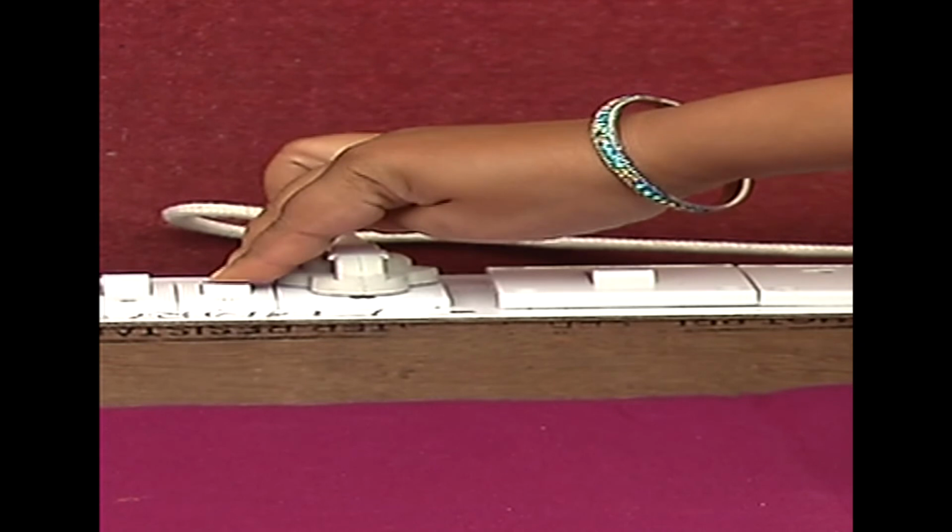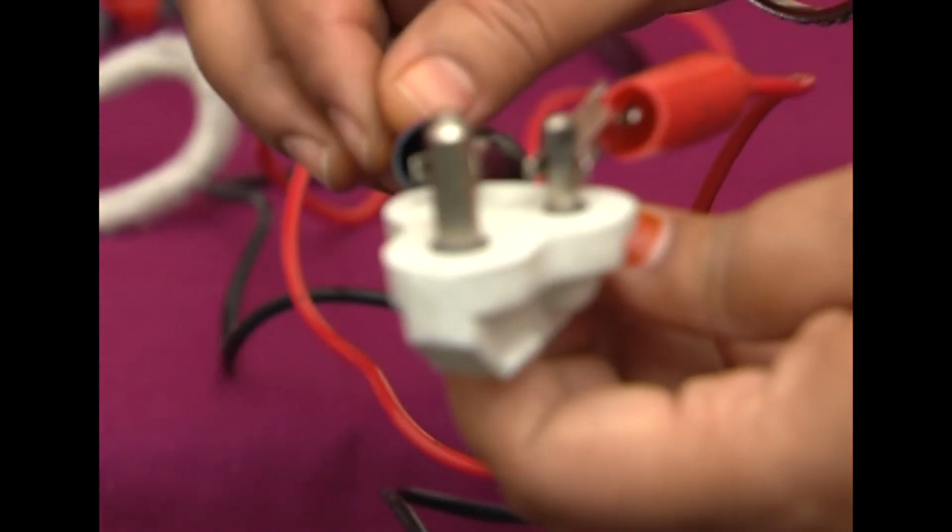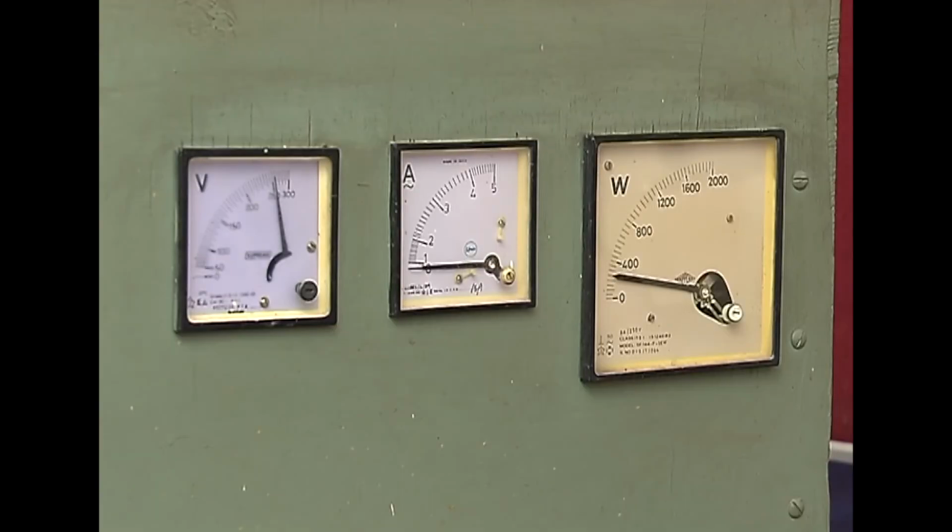Switch on the supply. Connect one end of the test rod to the body and note down the leakage current. Reverse the switch and note down the leakage current again. The observation and results say that if there is any change in the reading on the test board, it means that there is some current leaking when the equipment is in use.